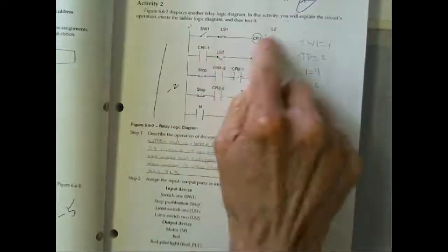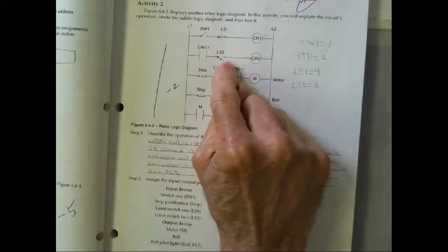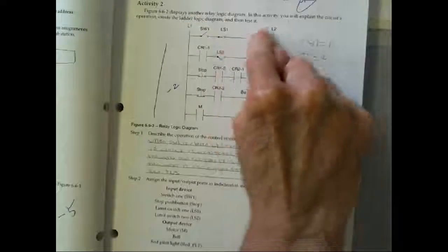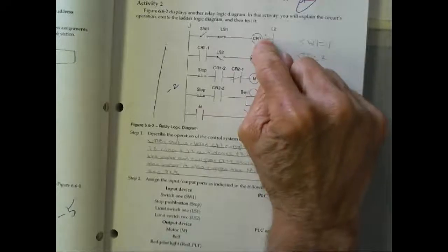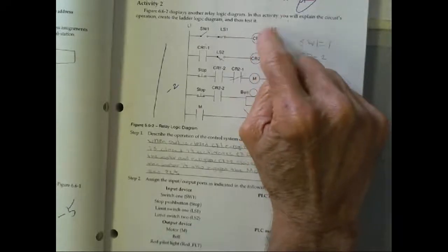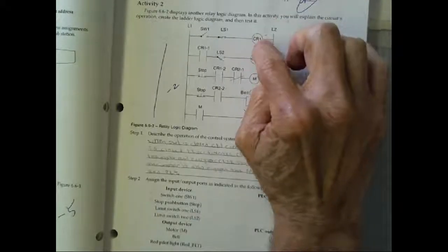It's a normally open contact because you don't have to worry about this. This is a contact controlled by a relay, so you use whatever symbol it says to use. This would be an input, right? Because this is coming up from a limit switch. All this is is a contact controlled by this guy up here. So if I call this B3 colon 0/0,